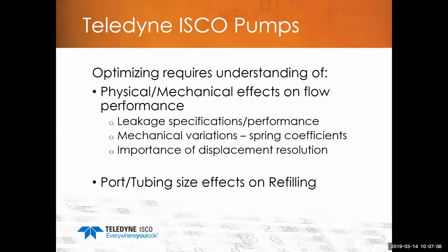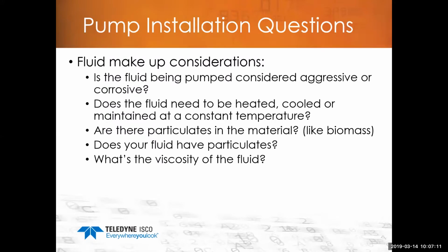More installation considerations, and considering the fluid. What is the material? I say fluid here, but it could be a different type of material that you're pumping. Is it aggressive? Is it corrosive? There are considerations you have to look at when you're trying to optimize your setup, using the correct material for the pump itself, whether it be a Hastelloy or maybe a titanium or something different.